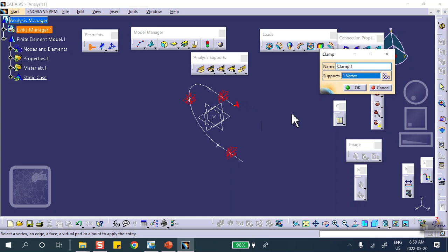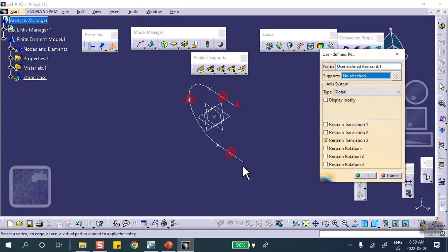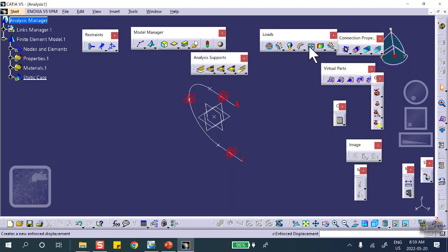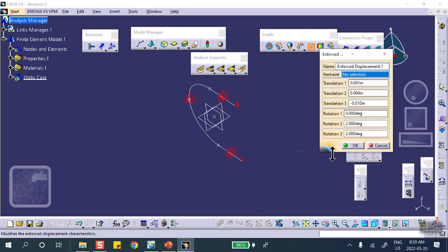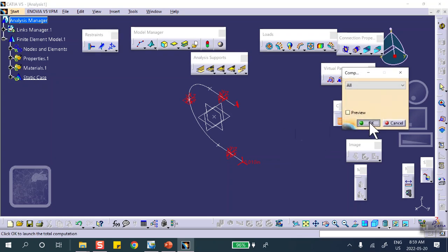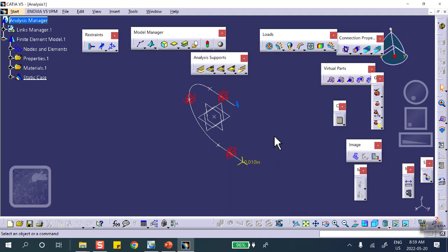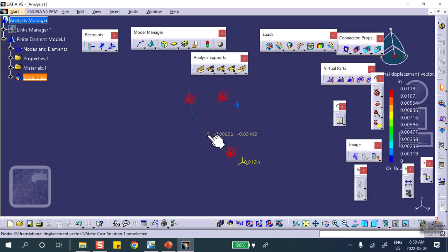And same story as before, you apply a restraint to this bottom vertex in the Z direction because you can change it. Same stuff here, so that's this. Good. And we're going to run it. Hopefully we didn't forget anything. I don't think we have. And displacement.